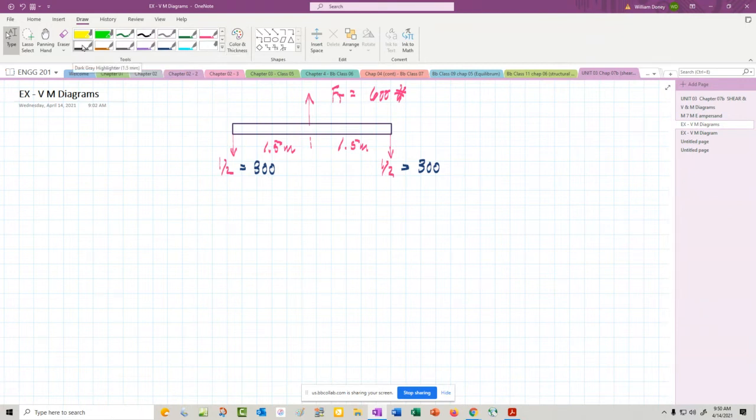While we're here, I have really already done the free body diagram, just by inspection. But if we had done the process, we would have done the free body. We don't have anything axial. We don't have any moments happening at the end because these are just hanging chains. So I did the free body and we found the support reactions. Check. Now we'll set it up. And again, this may be already done for you when you take a paper exam. On the computer, you would have to set this up yourself.